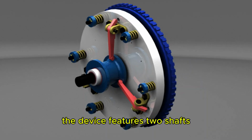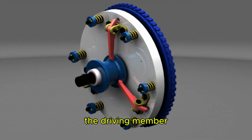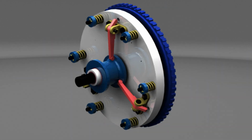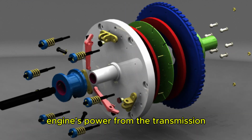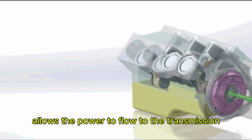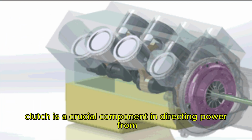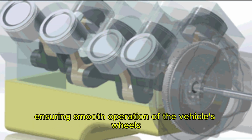The device features two shafts. One is connected to the engine or power unit, the driving member, while the other shaft provides the power output that does the work. In simpler words, a clutch is used to separate the engine's power from the transmission and engage it whenever needed. Pressing down the clutch pedal disengages the connection, and releasing it allows the power to flow to the transmission and the wheels. The clutch is a crucial component in directing power from the engine to the gearbox, ensuring smooth operation of the vehicle's wheels.